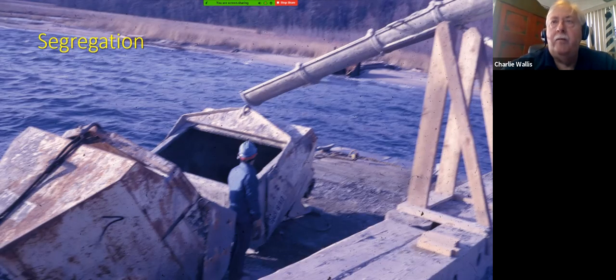We also want to avoid segregation. If you drop concrete a very large distance, the aggregate will separate out from the concrete and cement paste, and that's not desirable. So in this case here, there's an extension chute that was added to the concrete mixture to limit the amount of fall before the concrete was discharged into these buckets.